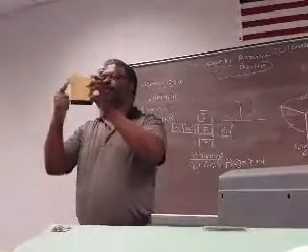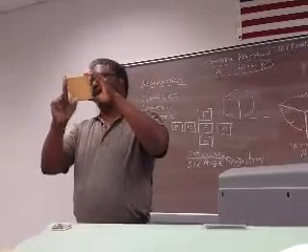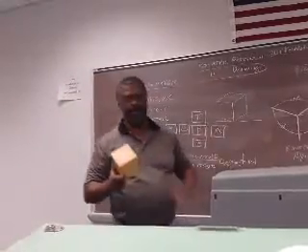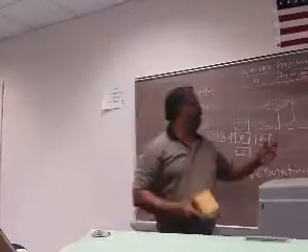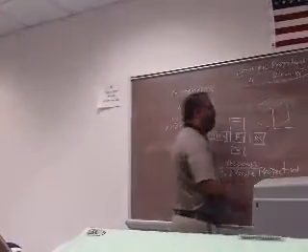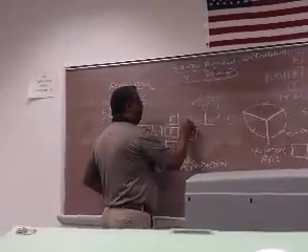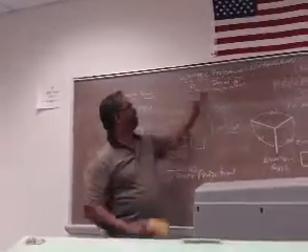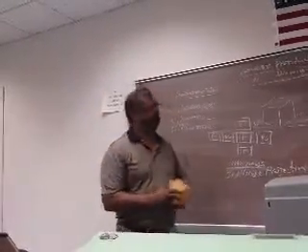Right now the edge is vertical, but as soon as I rotate him like this, the edge, even though it's now coming out at you, still appears vertical. And these lines appear to go back at an angle. We make that angle 30 degrees, and we get an isometric. So it's easier to draw an isometric than to actually rotate this in 3 dimensions and draw an isometric projection.